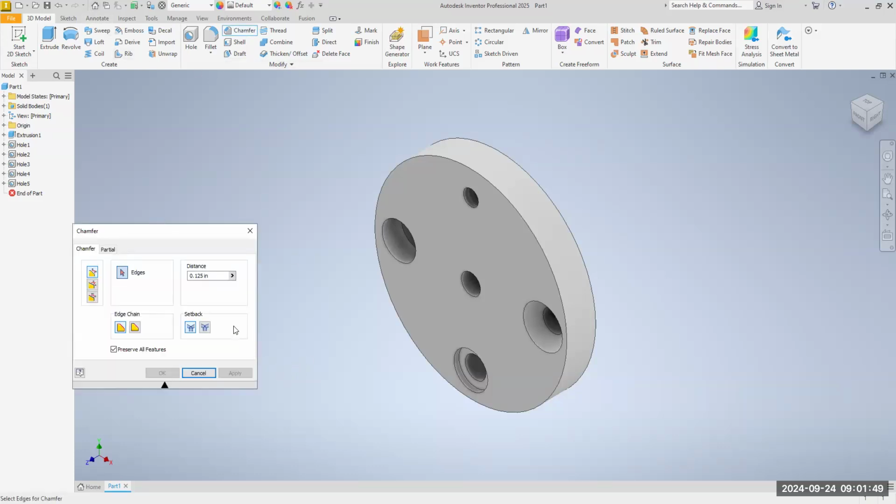and can you tell by the note on the drawing what is the size of my chamfer? Look in the right side view and tell me what the size of the chamfer is. Look on your drawing. I'm sorry, I have to talk louder. It's 0.03 times a 45-degree angle. Okay, it's 0.03 at a 45-degree angle. All right, so 0.03.